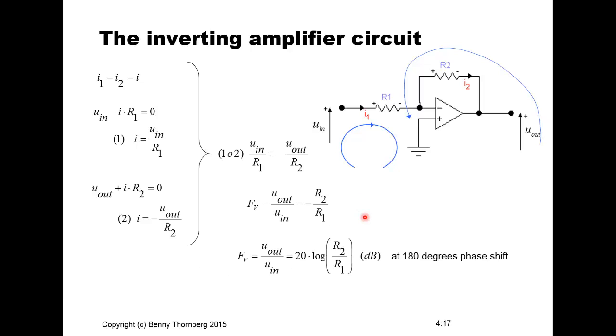We can alternatively describe it in the unit of decibel, and since we are comparing the voltage here, we are using the factor of 20 and adding the comment of 180 degrees phase shift due to this minus sign. A differential mode signal is a signal that you are measuring between two wires that are used to transfer a sensor signal, for instance. A common mode signal contributes the same on both wires. So you compute the mean value of the voltages that you can measure on both these terminals with respect to the ground. That is a very short introduction.